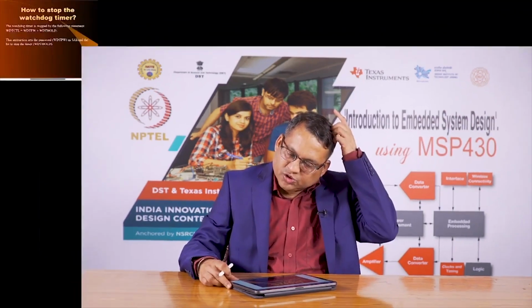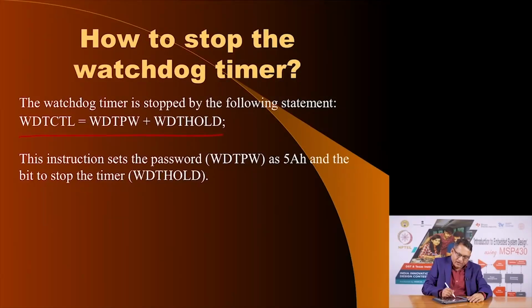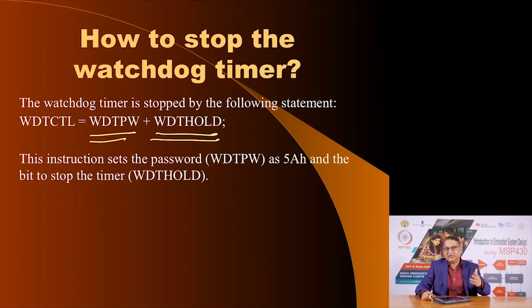So, you write a 0 and wait for some time and then check, is it still 0? If it is still 0, that means your oscillator is working. And so, this is the part I was referring to earlier. Let us see what we do now. To stop the watchdog timer, you simply write these two values into the watchdog timer control register. This part of the register is supplying the password, and this is telling it to please stop the watchdog timer, and we will see how it is used in our program example.